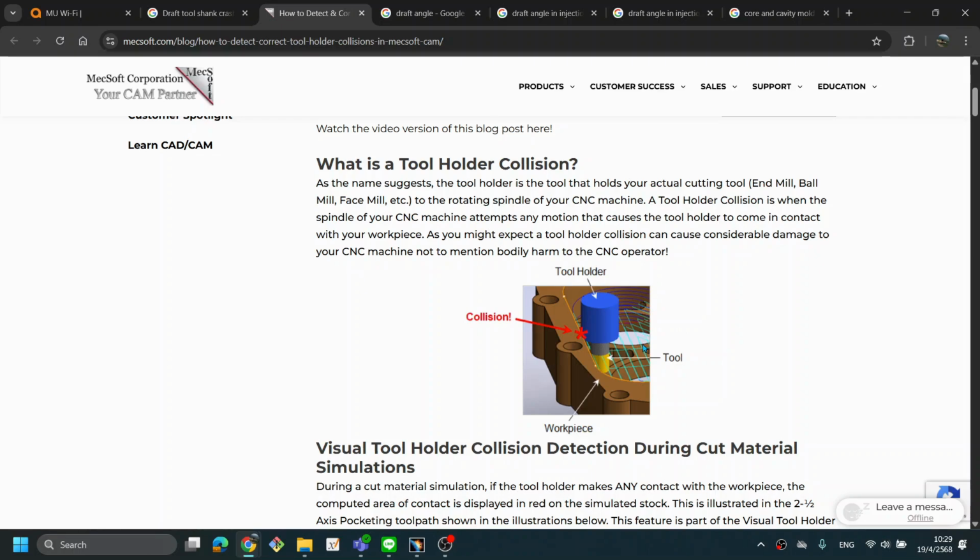Your part is not good, and the surface is damaged, right? Maybe you just adjust your part. In the video, I will address this and tell you again. Maybe the holder touches the shank of the cutting tool.